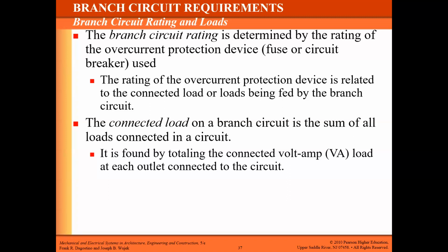And we figure that out basically by calculating all of the things that are going to be connected by wattage or voltamps. So the question might be, well, how do we figure out the wattage? Well, we can look up specific wattage of all the individual devices that we're plugging into our circuit. And that includes light bulbs, refrigerators, vacuum cleaners, all of these things that we draw electricity with. And then just add up all those wattages.